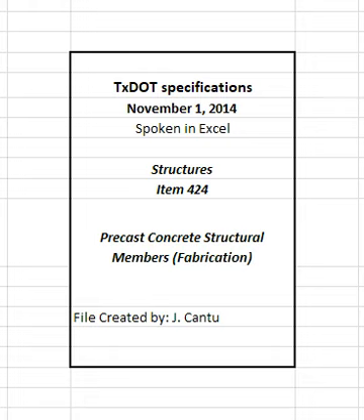Full-length debonding, when permitted, must be symmetrical about the vertical center line of the beam and limited to 10% of the total number of straight strands or 6 straight strands, whichever is less. Do not debond draped strands full length. When using a concrete anchor block to combine strand patterns, the same criteria apply. 4.2.2.3 Combined pre-tensioning and post-tensioning. When the plans call for a combination of pre-tensioning and post-tensioning, all of the requirements for pre-tensioning in this specification and for post-tensioning in Item 426, Post-Tensioning, apply.